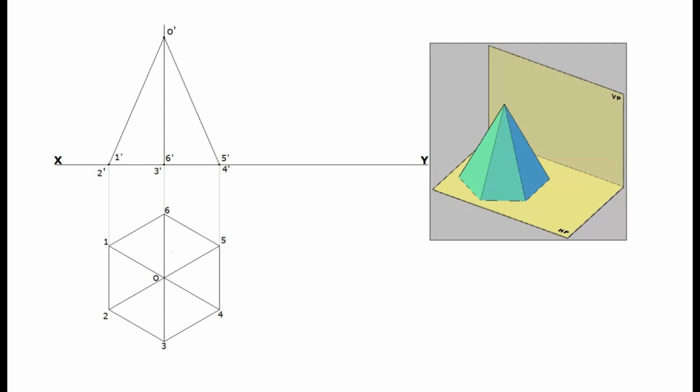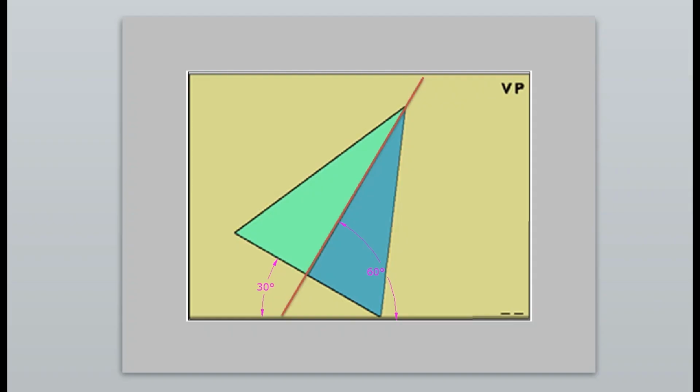By this, the first stage, that is, projections of the pyramid with axis perpendicular to HP and parallel to VP, are drawn. Now in the second stage, the axis is to be tilted for the given angle, 60 degrees. For pyramids and cones, maintaining inclination on the axis and completing the view is slightly difficult. Instead, the base of those objects can be tilted 90-θ degrees.